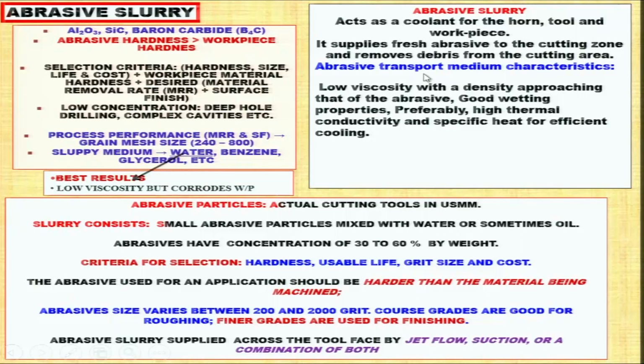Abrasive transport medium characteristics are as follows: low viscosity with a density approaching that of the abrasive, good wetting properties, preferably high thermal conductivity and specific heat for efficient cooling.